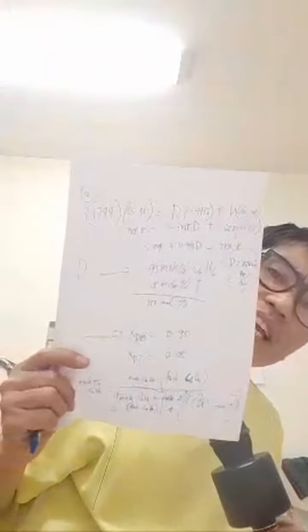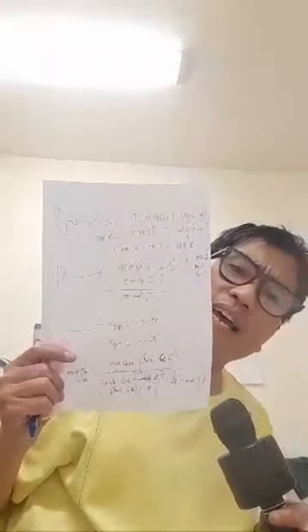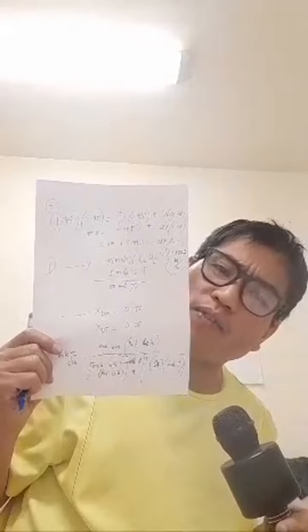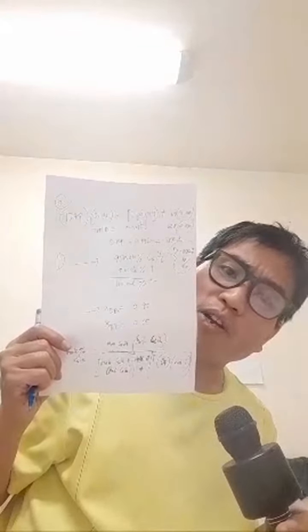So, bottom product or condensate is equal to 1744 minus distillate. Treat this as equation number 3. Now, substitute equation number 3 into the component balance, equation number 2, because in the component balance there is also a value of W. And you can now solve for D and W.